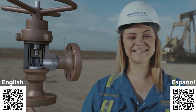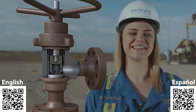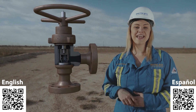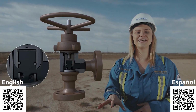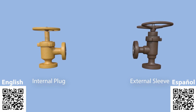This valve is best for high pressure drops and high sand concentration applications. The seat is moved to the outside where the fluid velocity is lower, reducing wear to the throttling surface and improving seat life. Reduction of valve outlet erosion is another important element of the external sleeve. It's achieved by directing the fluid exiting the throttling port into the valve trim and away from the valve outlet. Let's compare erosion in the last two choke valves.